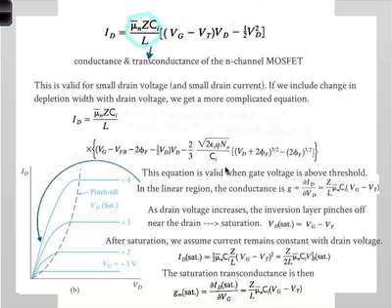So it's useful to understand what the saturation transconductance is, where the drain current, which is our output, is differentiated with respect to the gate voltage. This is the amplification factor overall. You can see it's not linear, first of all, because as you increase the gate voltage, you get higher amplification, which, by the way, could be a problem as well, which means you could distort your signal going in. So there are lots of things one needs to consider when you use these in devices, in circuits.